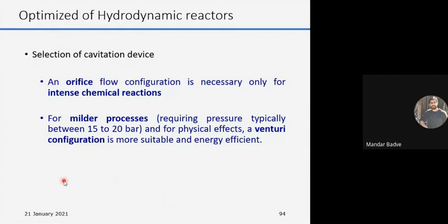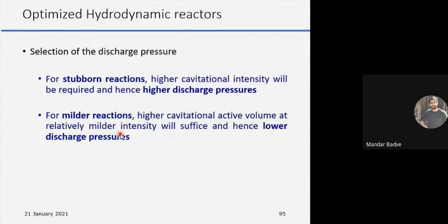So here, even the pressure values are still very high. Currently, what we have observed is that even at around 2.5 bar we are getting some effect. For nanoparticle synthesis, we have observed that even at 2 to 3 bar pressures we are currently getting nanoparticles using hydrodynamic cavitation. So obviously it depends on application to application, and the pressure and geometry can vary.